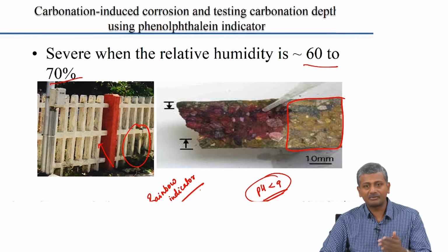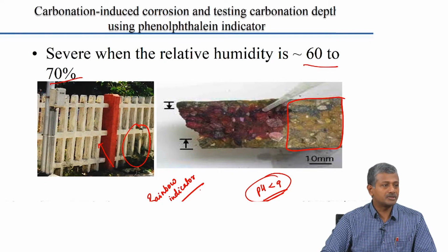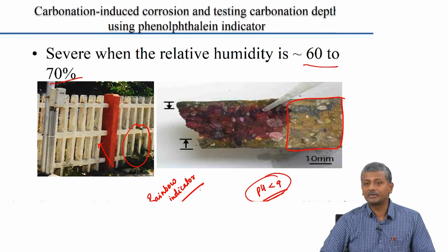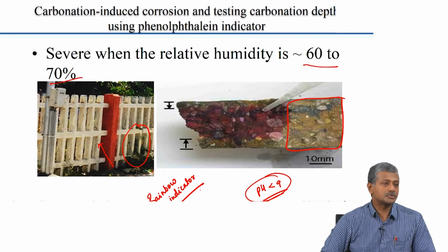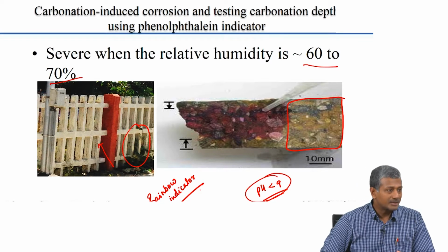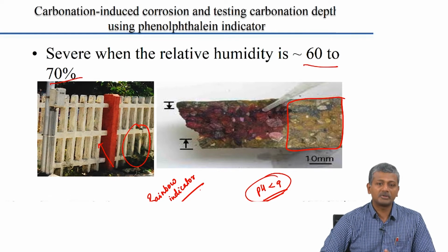So, you have very many different colors based upon the actual pH inside the concrete. Whereas, phenolphthalein wants that pH to be much less than 9 to create the colorless condition. So, indication of carbonation depth could be a critical factor in looking at concretes in the field and trying to understand their propensity for getting corroded.